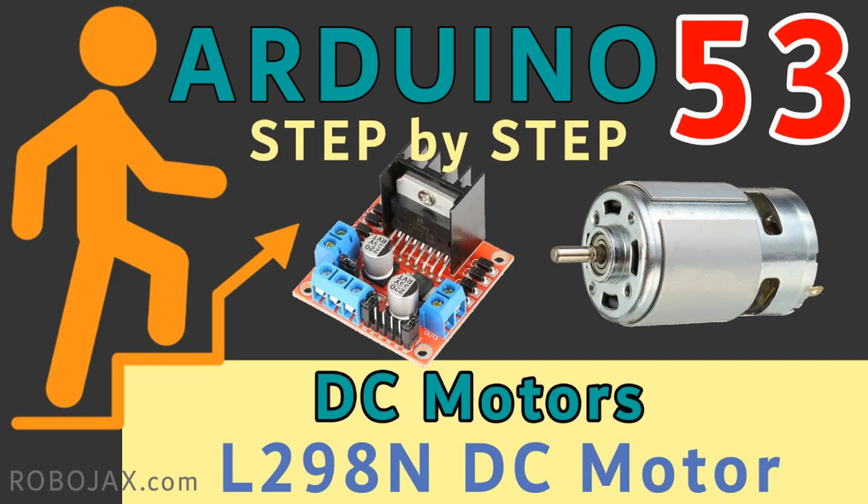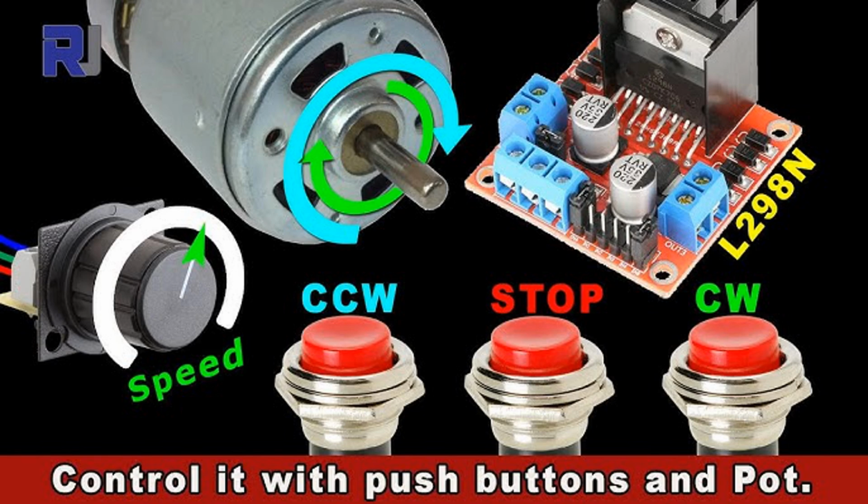8. Disadvantages of universal motor drivers. Limited efficiency. Universal motors are less efficient compared to other motor types like induction or brushless DC motors. This can lead to greater energy consumption and heat generation. Brush wear. Since universal motors are brush-type motors, the brushes wear out over time, leading to maintenance needs. Noise. Universal motors can be noisier than other motor types, which can be a concern in noise-sensitive applications. Limited speed range. While universal motors can be controlled for speed, they are typically not as precise as BLDC motors or AC motors in certain applications.